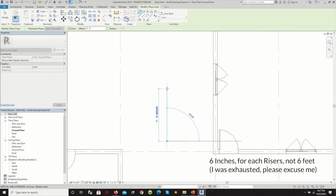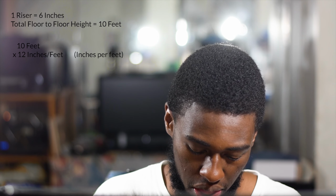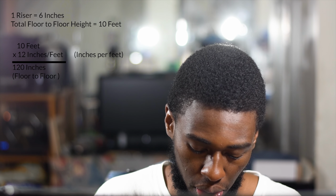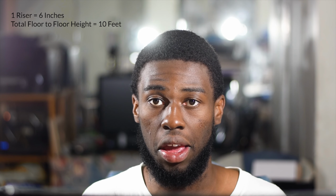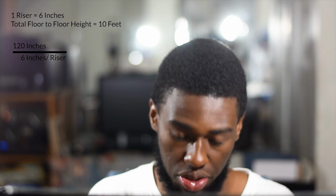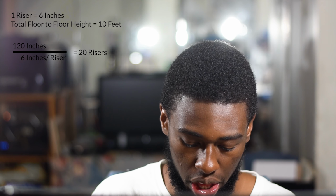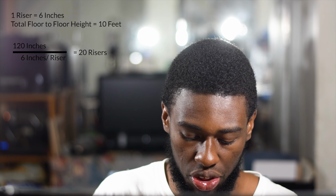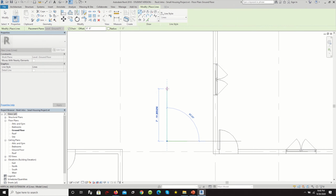So my rise over run, if we do some quick calculations right now, so 10 feet ceiling height, we know in each feet is 12 inches. So it's 120 inches floor to ceiling. And if we want our risers to be, let's say, roughly 6 inches each, we'll have to divide 120 by 6 inches to figure out the number of risers that we're going to need. So 120 divided by 6 will give you 20, and the inches cancel out one another. Therefore, you're going to need just 20 risers. So we're going to need 20 risers in order to actually accommodate this.